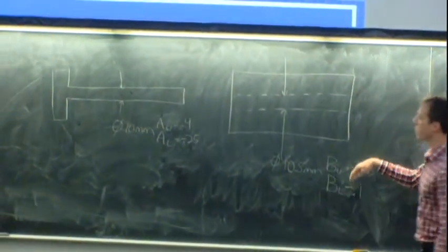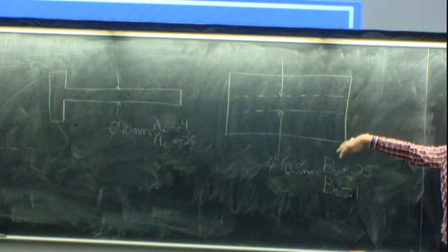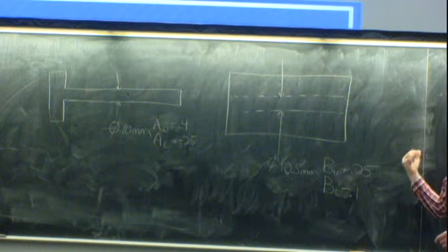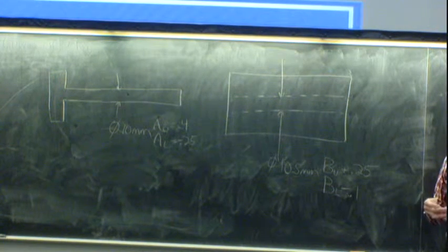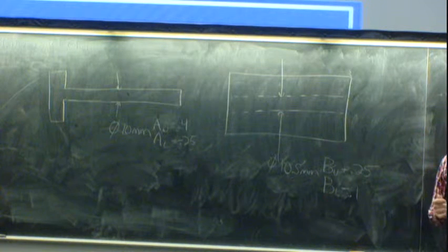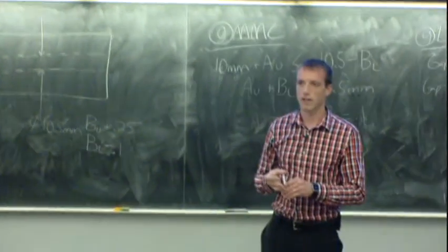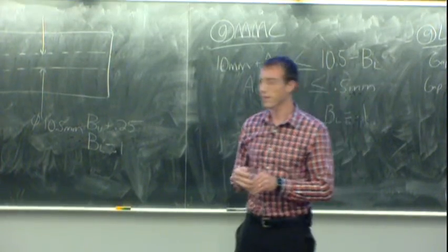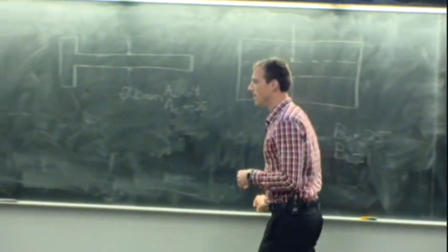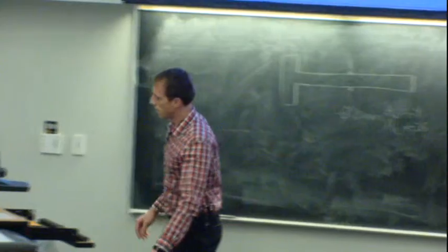So that's how you could come up with a set of tolerances for those dimensions based on not allowing interference at the top end and giving a millimeter of slop at the least material condition. Does that make sense to everybody? Math's pretty simple if you get where I'm pulling the numbers from. Does anybody need to go over that again, or good? It was interesting enough that time? Okay. Good.